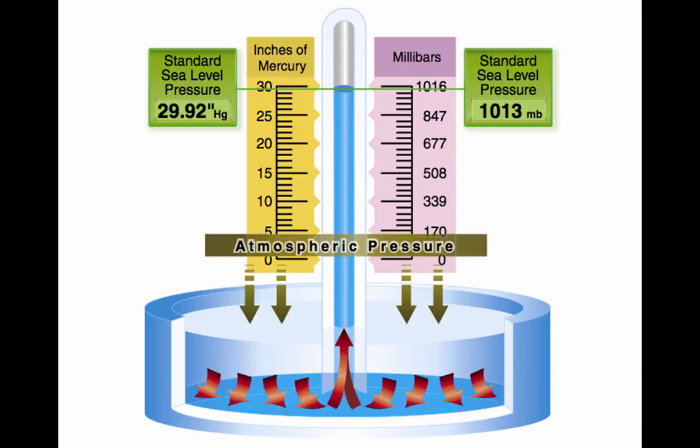Air, like any other fluid, is able to flow and change its shape when subjected to even minute pressures because of a lack of strong molecular cohesion. Though there are various kinds of pressure, pilots are mainly concerned with atmospheric pressure. It's one of the basic factors in weather changes, helps to lift the aircraft, and actuates some of the most important flight instruments in the aircraft. These instruments often include the altimeter, the airspeed indicator, the vertical speed indicator, and the manifold pressure gauge.